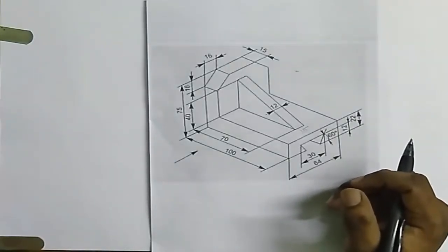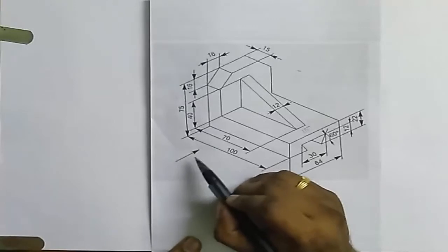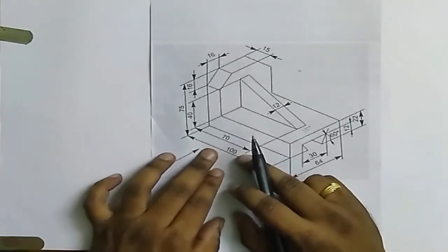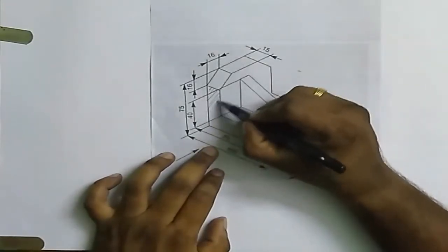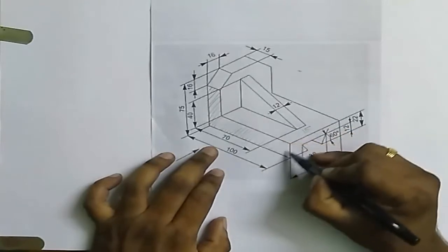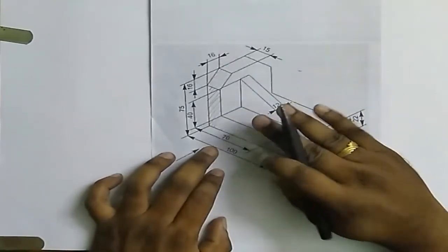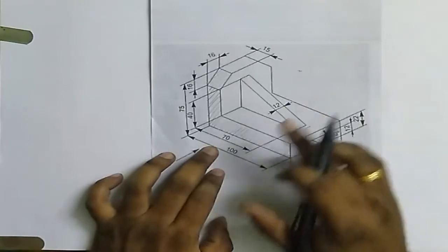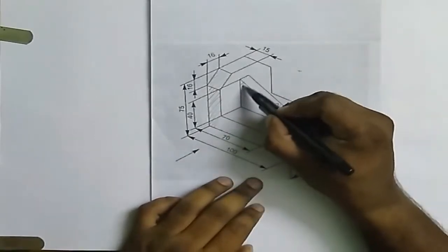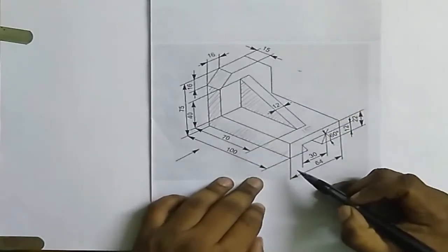As you saw in the video, this is your front view direction, since the arrow mark is given in this direction. In the front view, this surface will be entirely visible, as you have already seen in the video. Similarly, this angled surface will be viewed as a rectangle or square in this direction. This entire surface will be visible and also this surface will be visible. First you have to notice all these things, then we can start drawing the front view.